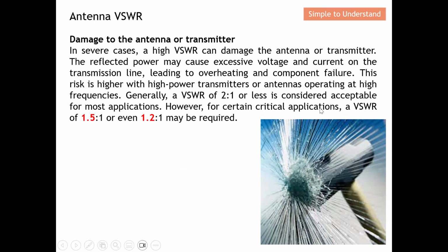However, for certain critical applications, a VSWR of 1.5 or even 1.2 may be required. So in certain niche areas, we want the VSWR to be as small as possible, even as small as 1.2 for certain critical applications.